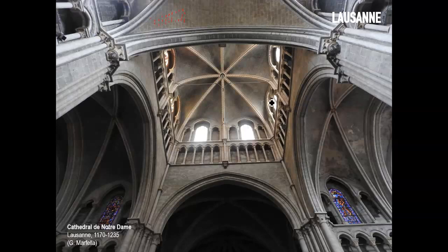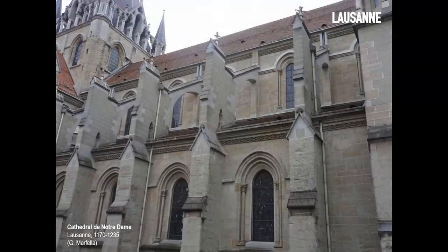And you can see how every vault, including the intersection of the nave and the transept, is always vaulted with ribs and all that. And then from outside, now you can see still the same structure, very simple, much smaller than the giant cathedrals of Amiens and Reims and Bourges and Chartres, certainly, but still, clearly this is the position of the ribs. These are the arches that define the flying ribs and the pinnacles and the buttresses that eventually help to reconvey all these loads down below.